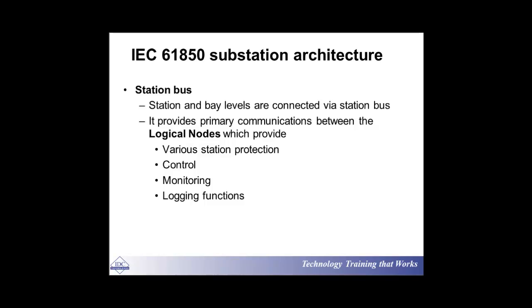And as a result of that definition, you as the system designer will program the system. So when you say I am in the business of programming 61850, it means that you are first of all understanding the identities and attributes of each node, and then your knowledge base is like you have got the capability of mapping all this information into this station bus in the language of the machine.